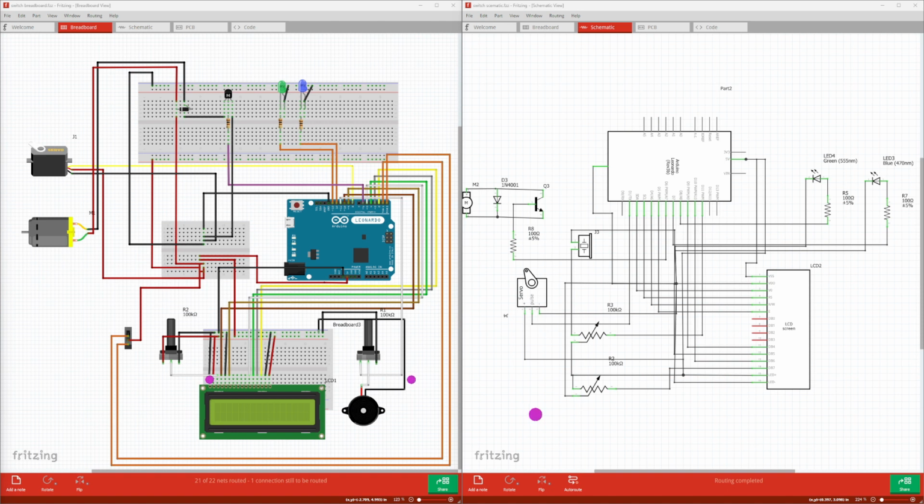The potentiometers. A potentiometer is a variable resistor. We can use an analog input to measure the potentiometers. In this project, they are used to control the amount of current going to the LCD screen for contrast and the piezos for loudness. The potentiometer has a ground pin, an input pin, and an output pin.